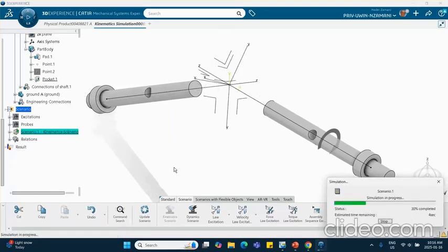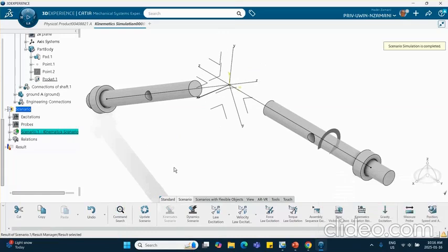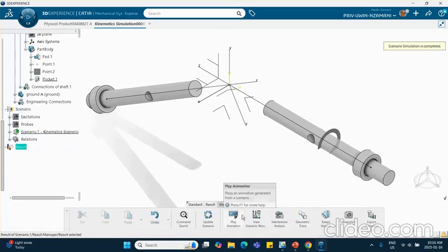Time. Obviously 3 turns. Okay, let's plot the result. Let's plot the angular velocity of this shaft, the driver one, and the driven. Driver one should be constant. Driven one will not be constant. That's the way universal joints work.